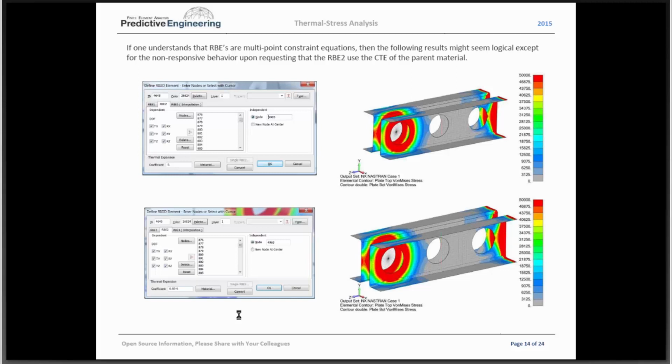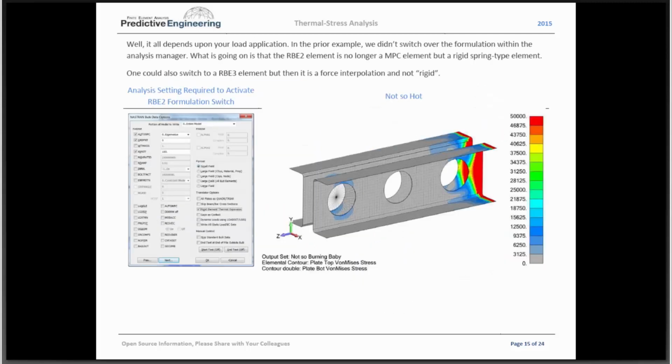Adrian, all clear? Yeah, I got one thing to add. Whereas with the materials we get a reference temperature, with the rigid element we do not. I think it might use 0 as a default. I think I've had certain scenarios, you're right, where maybe my starting temperature was 70 and I wanted to go up to 200, but I would want to use rigid elements.